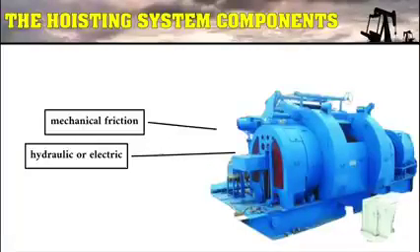An integral part of the drawworks is the transmission system. This gives the driller a wide choice of speed for hoisting the drill string. Drawworks has two catheads, used to spin and tighten the drill pipe joint. The drum is housed in the drawworks and transmits the torque required for hoisting and braking.